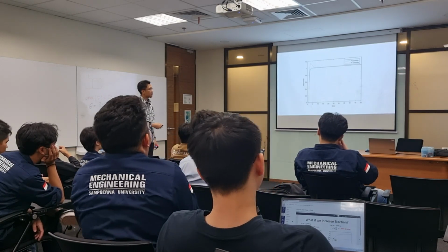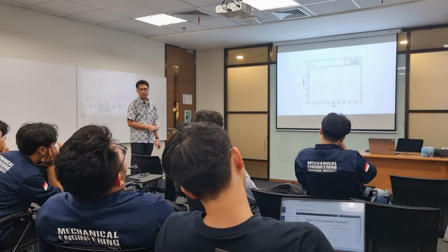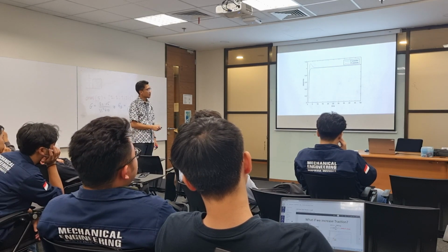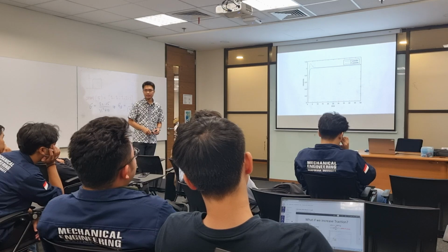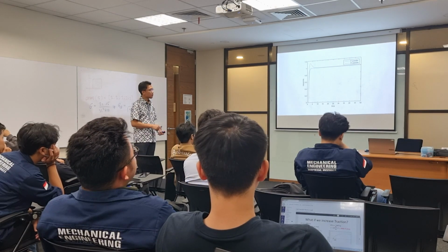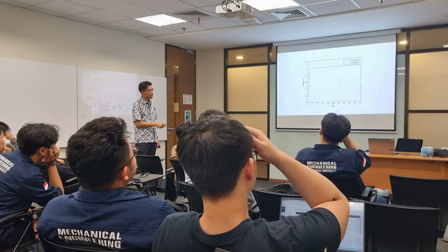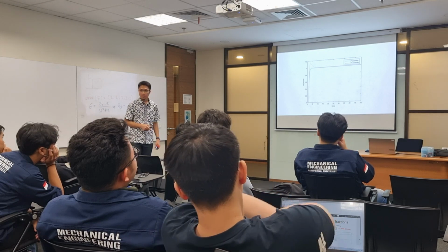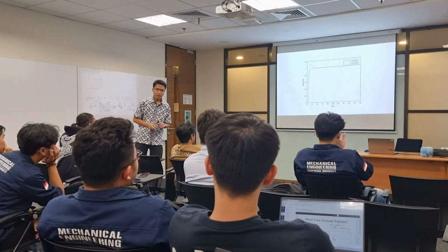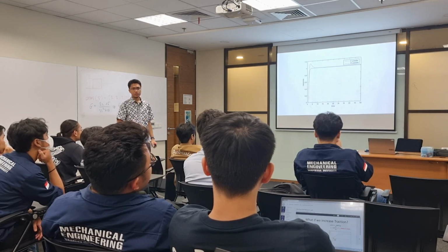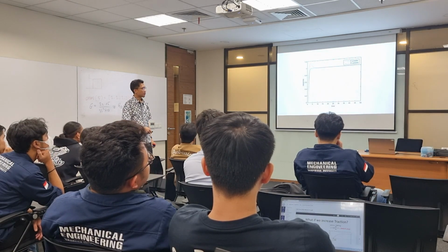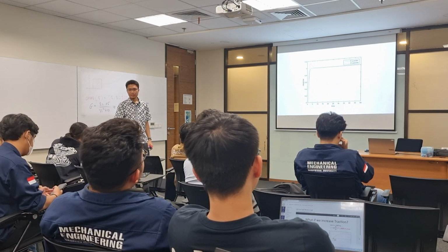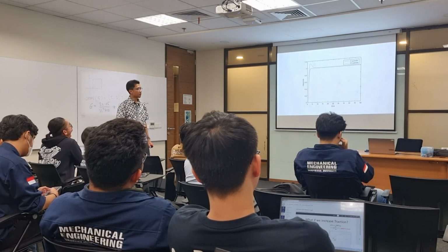So let's see the simulation result. This one, the result. Yeah. What we notice here, the proportional controller has a steady state error. Okay, although very small, we can see there is a steady state error coming from the proportional controller. The PI controller has zero steady state error. However, there is an overshoot over there. And this overshoot is very difficult to be eliminated. Yeah, that's one of the drawbacks.